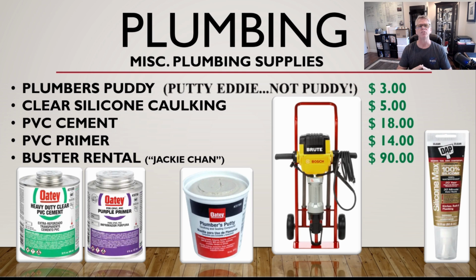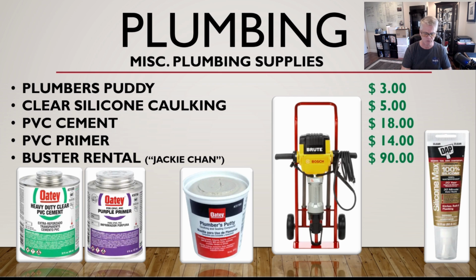Now, we use a sewage ejector that goes in the floor, and our drain lines are under the concrete floor, so we need to bust open the floor with the buster to expose a trench for all of our drain lines beneath the concrete floor. So you're going to need a buster, $90 for a rental for the day. You'll also use the buster to jack the hole for the sewage ejector, because the sewage ejector basin goes in the floor, beneath the concrete floor. So the buster's $90 for the rental.